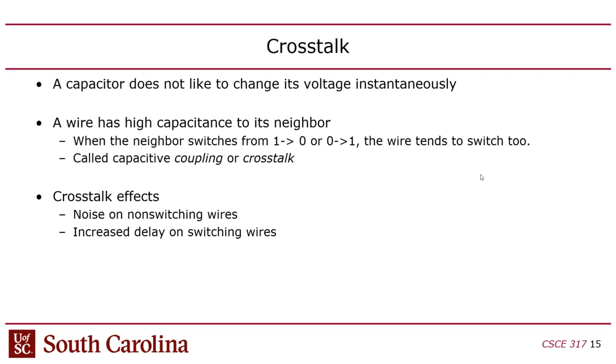Now, normally you have these capacitors to ground, right? And so when you have a wire that's above a ground plane or above the substrate, and it's switching, you generally expect that the ground part is going to stay at ground, because when you connect the substrate of a chip to ground, you've got a lot of connections. There's a lot of contact points, right?